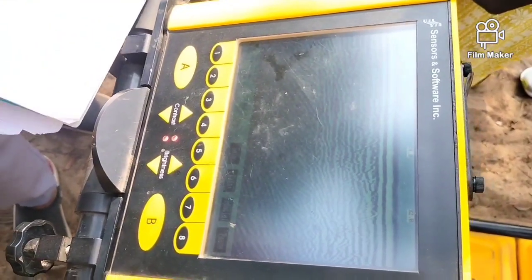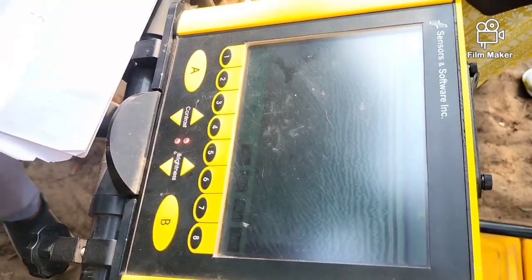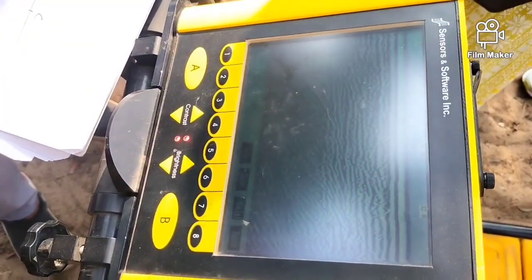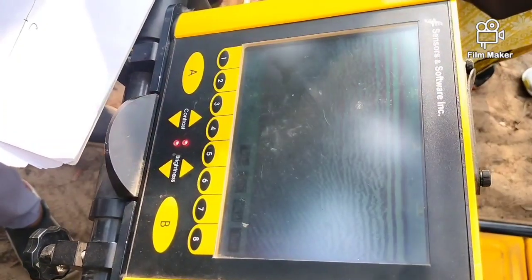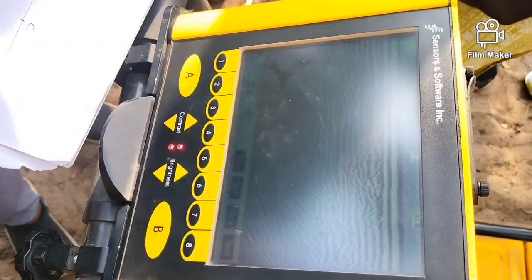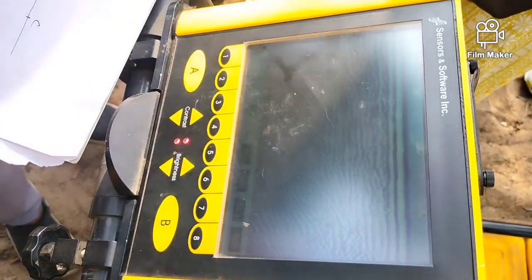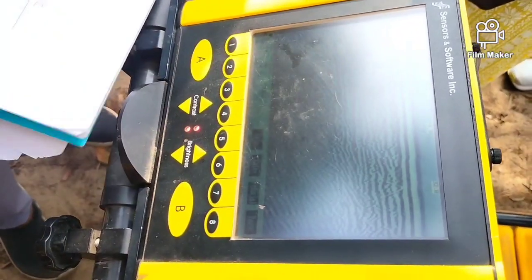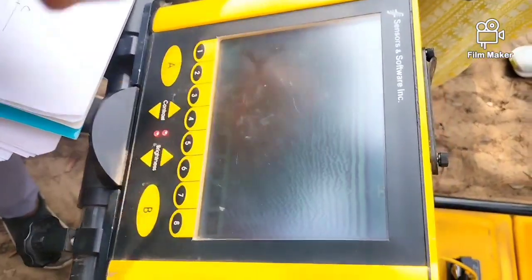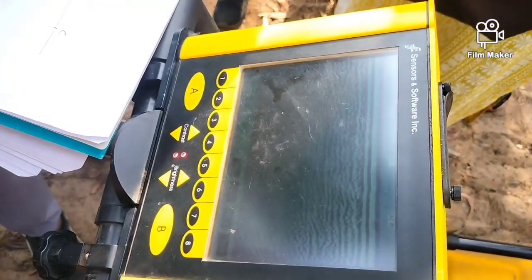It could be a pipe also. If the pipe is going perpendicular to the GPR transect, then you would cross it, but it'll be just a point crossing, right? So you would see a pipe as a hyperbola when you're crossing perpendicular to it.